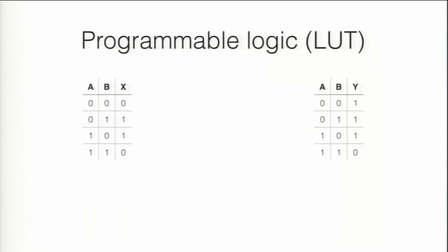On the right-hand side, you see, I don't know, a NAND. Yep, perfect. So you got the idea. Now that you know that you can build a NAND, you know that you can build every possible logic circuit with just those lookup tables, as they are called.